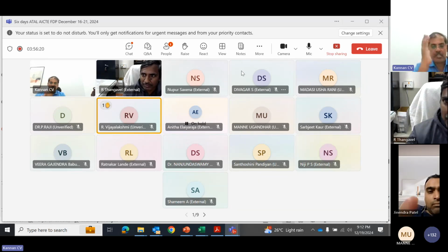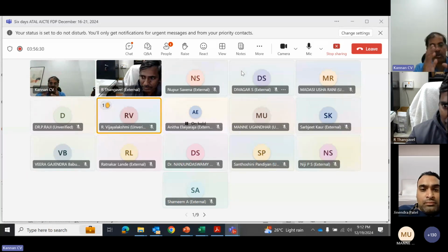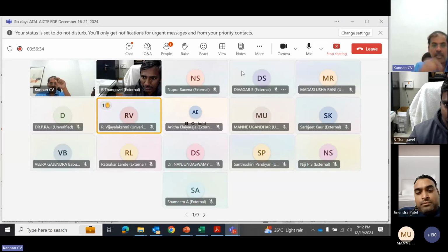polycrystalline silicon, automatically there is less of that, because the growth process also takes longer time. It's a slow growth process, right? So even the impurities and dislocations, all those things will be better in electronic grade. And you can also measure the impurity concentration, iron content, copper, all the metallic impurities.